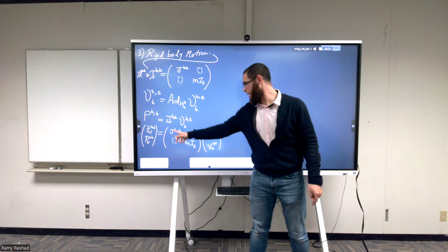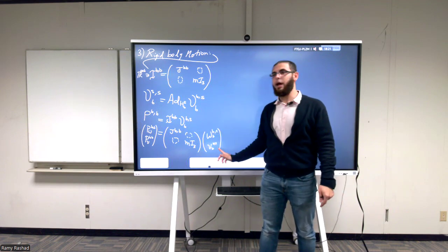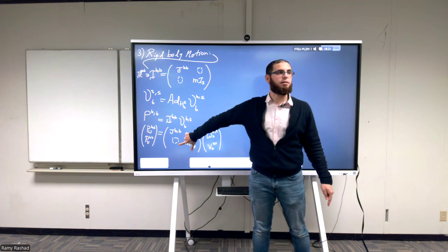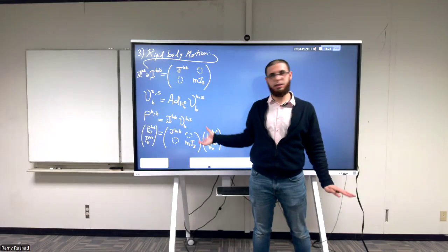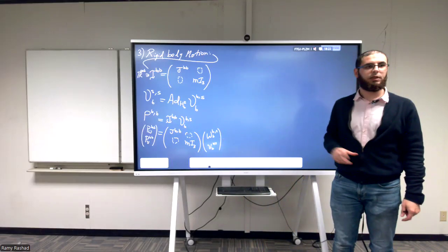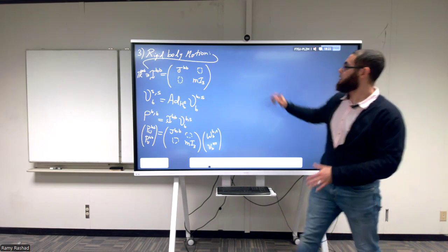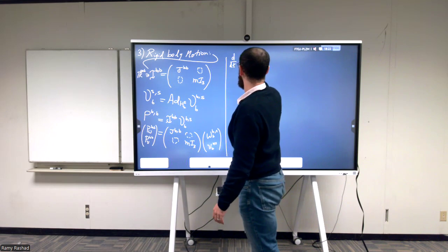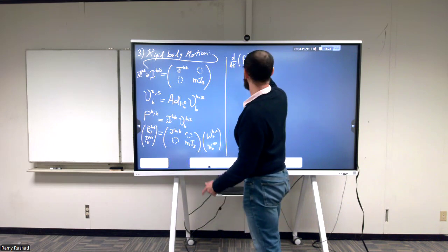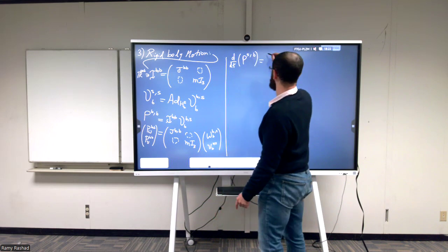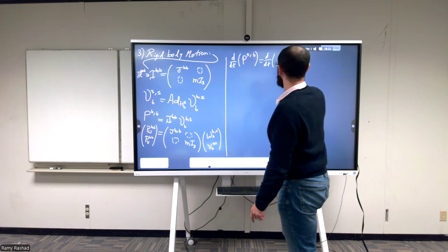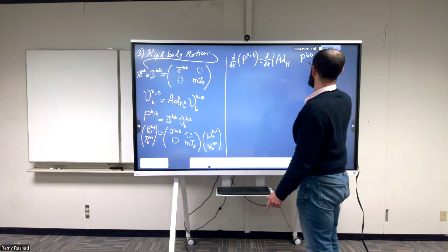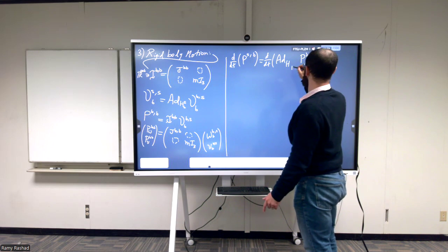It's no longer just J multiplied by omega and M multiplied by V. Only if this is placed at the center of mass is that truly the case. So this is why this is more general. Clear? Okay. So the rate of change of momentum expressed in the S frame is simply the rate of change of the adjoint transformation of P_B from B to S.